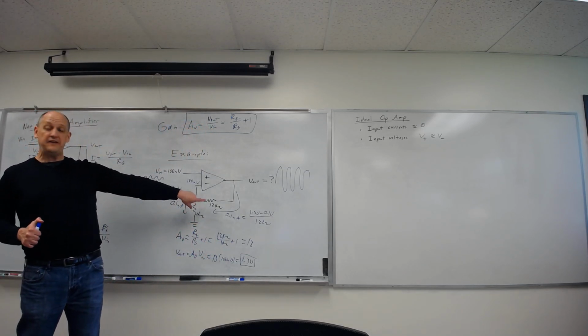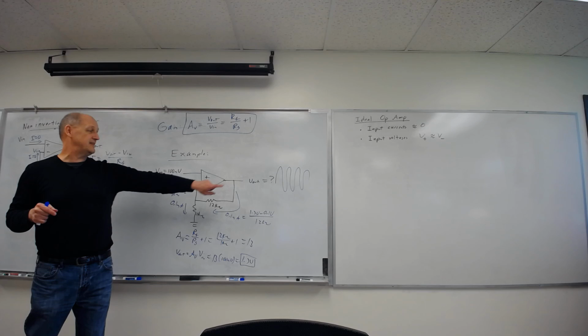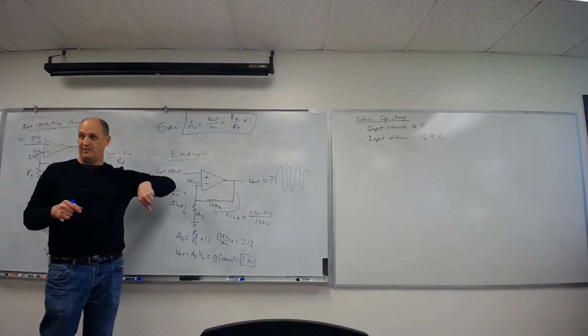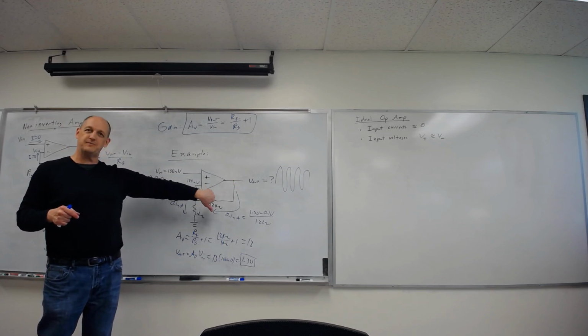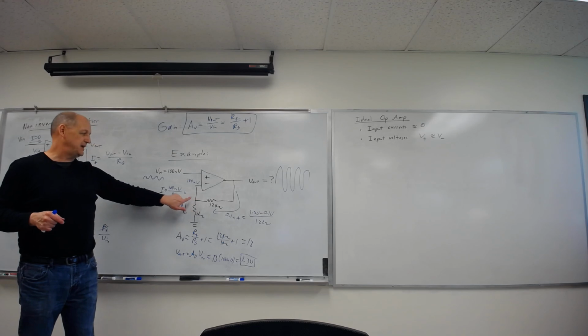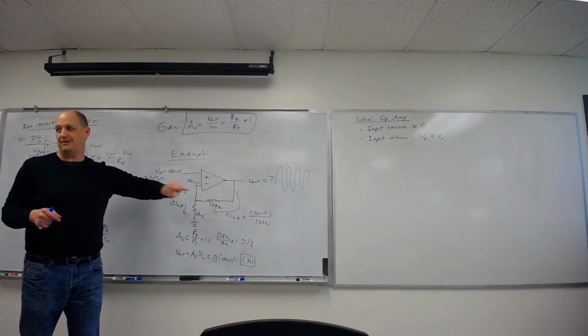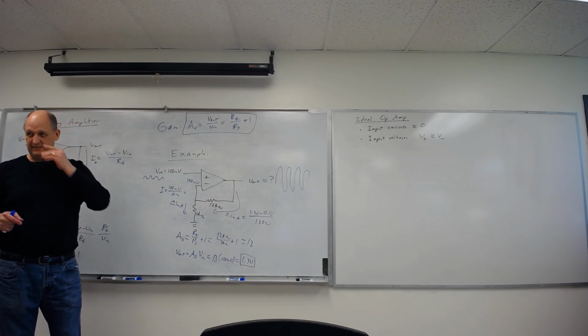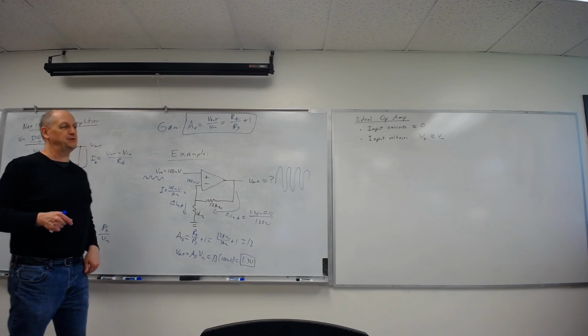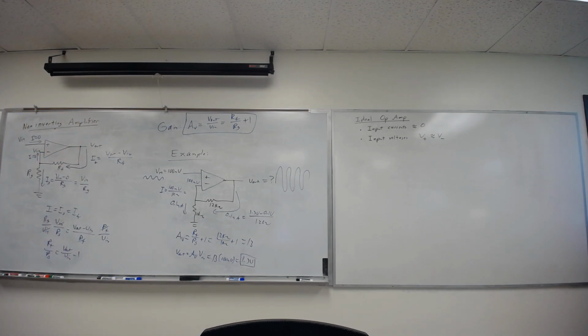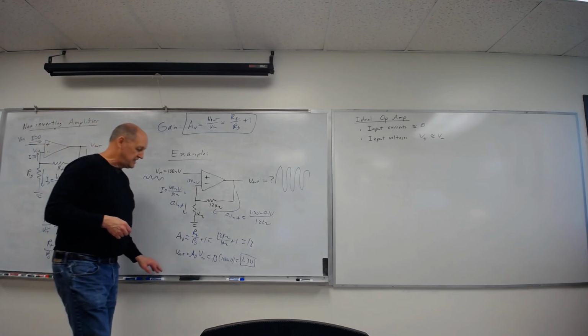Do not forget on the feedback resistor, it is very tempting to take this voltage minus 0, but it's not. It's the voltage across this resistor. So it's that voltage minus this voltage over that resistor. And you should get exactly the same current for both.